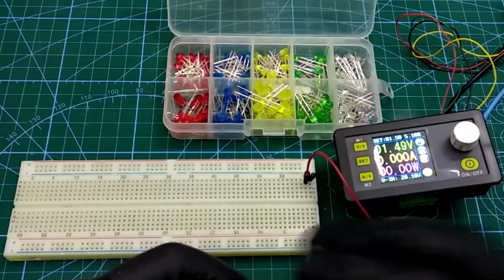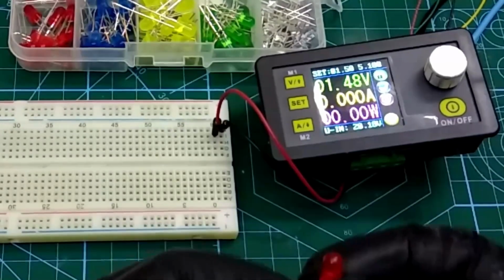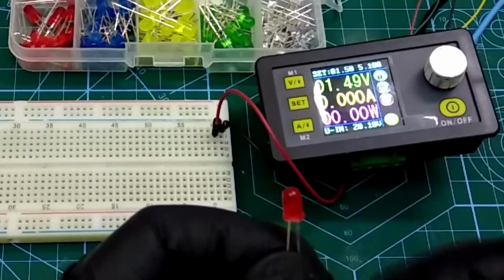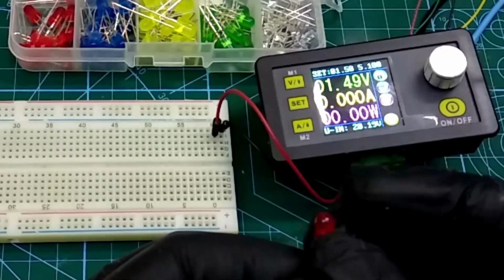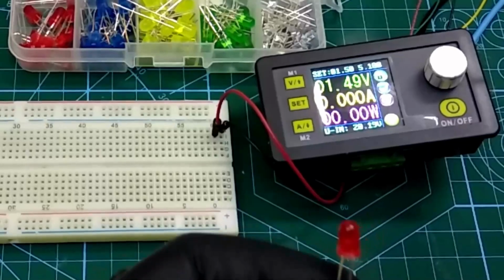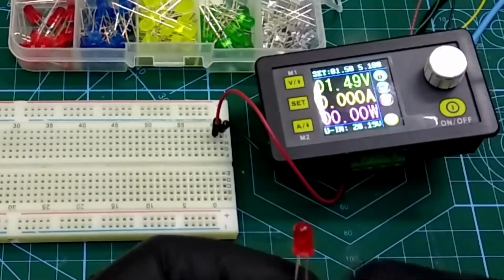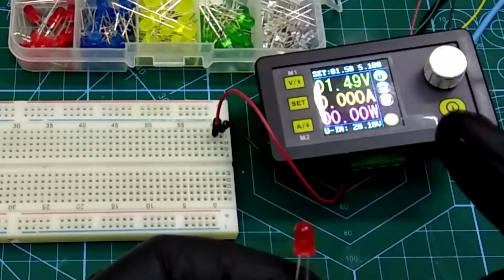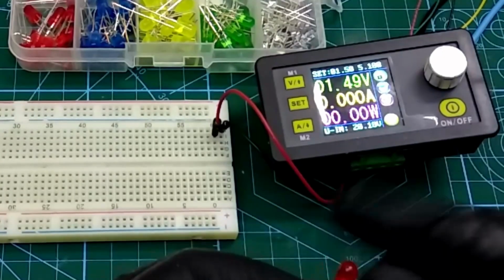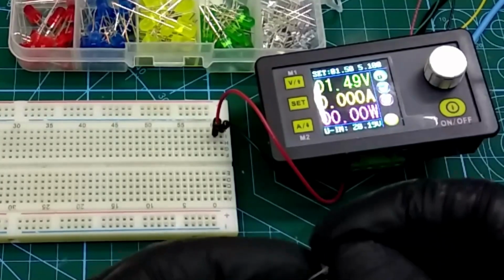Well, before starting the video I have to clarify that an LED diode is not a resistor, it's a semiconductor. It's a junction where photons are produced, so it needs a threshold voltage to work. It is not like a resistor that you put more or less voltage on and a more or less proportional current flows. There has to be a minimum voltage in the LED diode for electric current to flow and produce photons. An LED diode starts at approximately 1.5 volts, well, a little more than 1.5 volts.